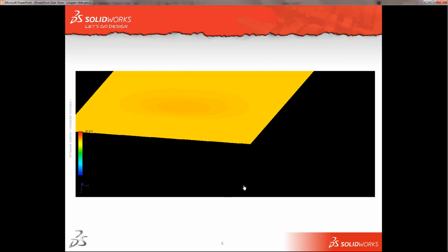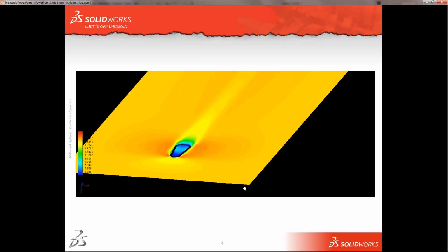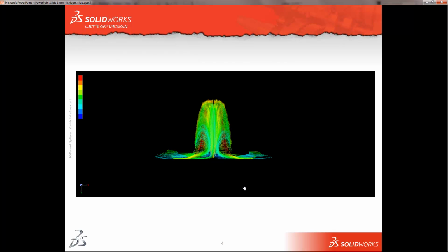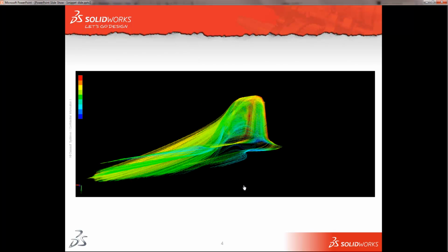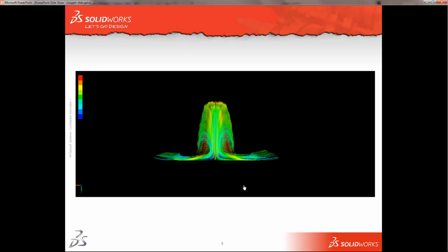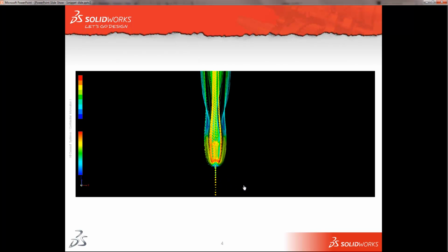and running the study. We've got, first of all, our cut plot moving down through a turbulator, and then we can change the angle for a front projection and see the flow trajectory. Change the angle again and repeat the flow trajectory play. And you see we can keep changing that angle and repeating it, and setting up the animation beforehand. You can get a really nice video.